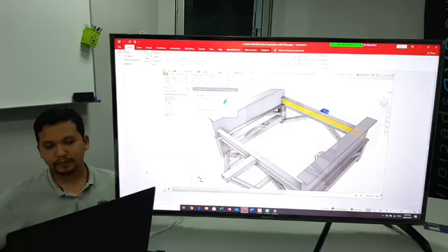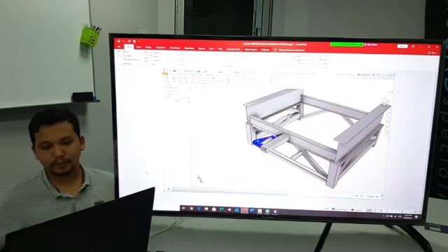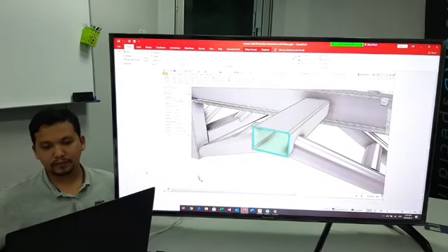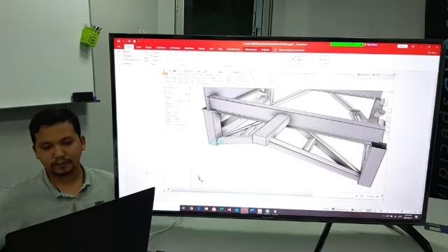Design changes are now easier with the ability to select multiple members with the remove end treatment command. Close off structural frame members with the new insert end cap command. You can set the position, profile shape, and thickness, and save the properties of your end caps as presets for later use. And finally, you can now add custom end cap families to your Content Center library.